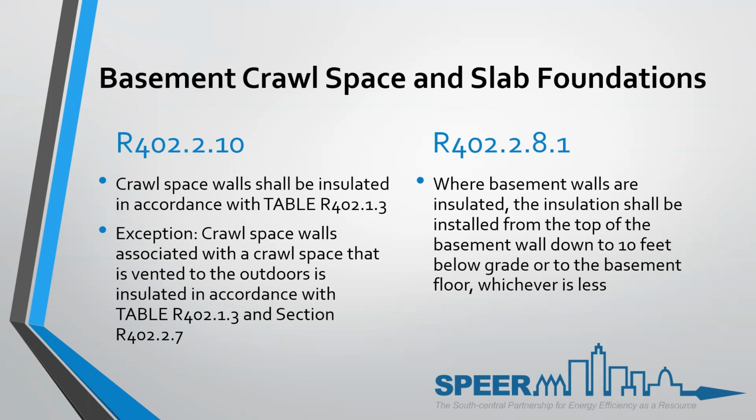So R402.2.7 basically says the insulation shall be installed to maintain permanent contact with the underside of the subfloor. We talked about that a minute ago, but being installed permanently with either staples or wire stays, not just friction fit, allowed to be falling out later on. In accordance to the manufacturer's instructions, and maintain the R value and readily fill the available cavity space. So if it fills it fully, you don't have to do the permanent stay.